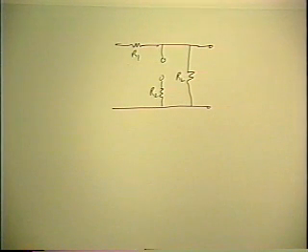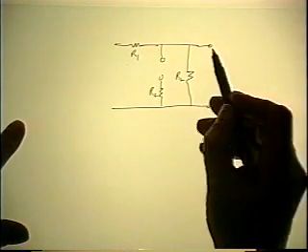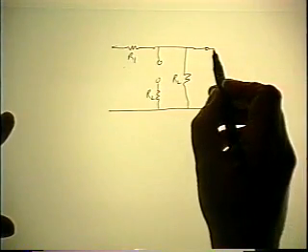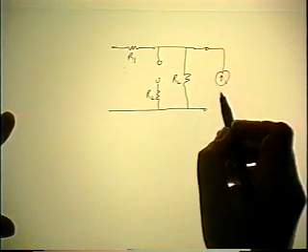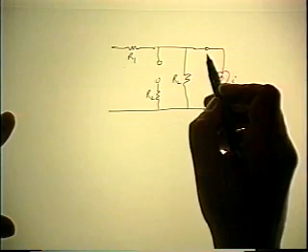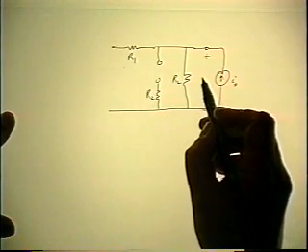And the first thing to do is to identify correctly input and output. The function we're calculating is output impedance. So we're going to drive the output with a current, so I'll call it I_O, and we're going to develop a voltage across it, which is V_O.